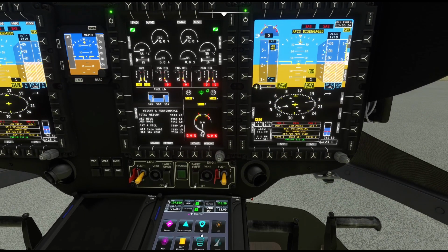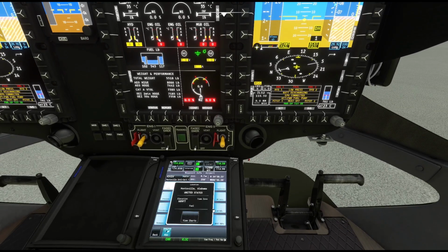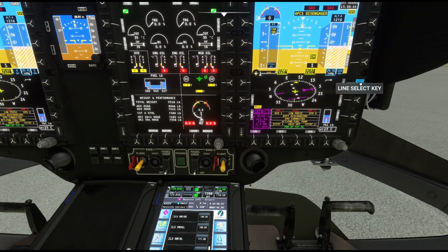And actually, I'll tell you what, let's just do nearest airport. HSV frequencies, we will grab that and pull it down. Let's just bring an ILS in, and boom, there we go. Now we have a course deviation to the ILS. We are not in line with the localizer of the ILS. All right. Now, on top of that, we can place additional information.